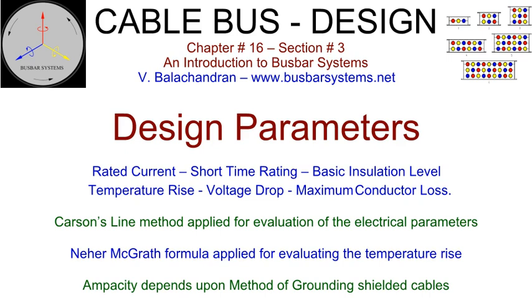As explained, the current and temperature distribution across the cross-section will depend upon the geometry, interphase and intraphase spacing of the conductor. Most manufacturers have a computer program that calculates resistance, considering skin and proximity effect, reactance, self and mutual, current distribution, and electrodynamic forces. The earthed enclosure around the cable matrix will impact the values of these parameters.